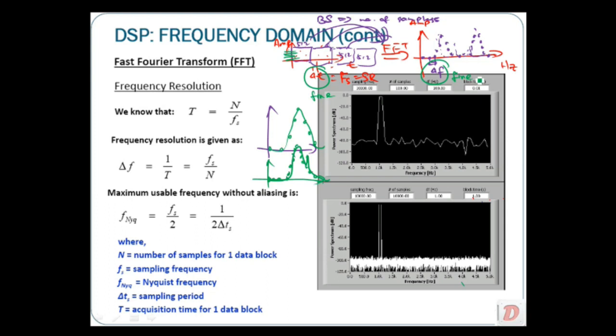To know our frequency resolution, delta F, basically it is our sampling rate, Sr, divided by our number of samples in the block, which is the block size. Or F max over delta F, which also equals F max over our FFT lines. This delta F defines how accurate our frequencies are when the digital samples are transformed to the frequency domain.